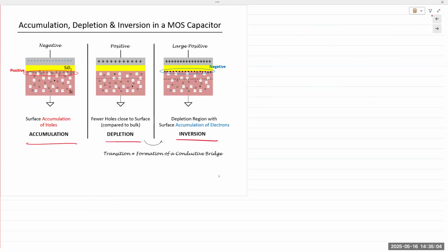All right. So we have a P-type material. In a P-type material, if you apply a negative voltage, it is going to attract all of the holes. If it attracts all of the holes, you now have a channel full of holes, right? It's attracting all of the holes right at the surface of that semiconductor device. So you have a pathway, a highway built of holes. But it's a highway built of holes, so only holes can traverse through it. Electrons cannot.